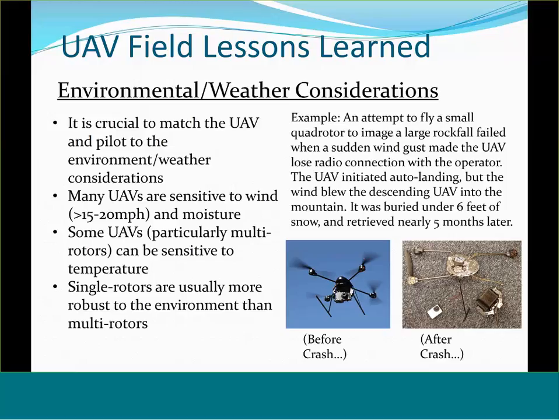We've flown our single rotor helicopter in wind gusts of 50, 55 miles per hour, and it has had no problems at all. And again, we believe that's due to the large polar moment of inertia of that single blade that's spinning. But if you're not careful with these things, you could have the same thing happen to you that happened to us. For instance, we tried to fly a large rock fall near Salt Lake City with this small little UAV. Unfortunately, that day there happened to be a winter storm up in the mountains.